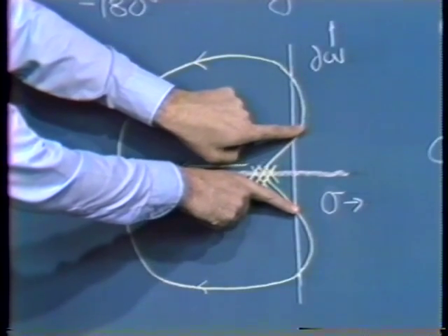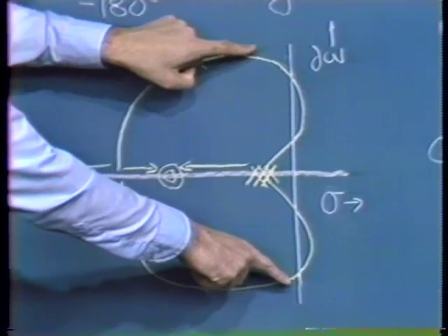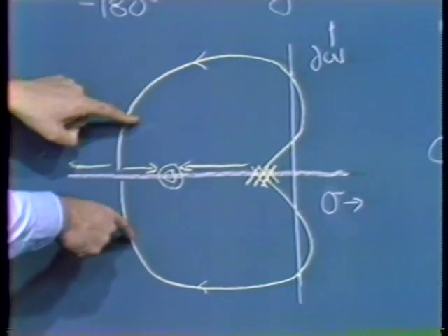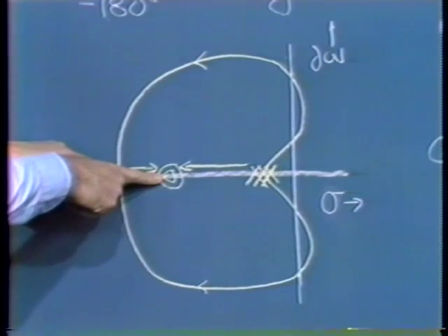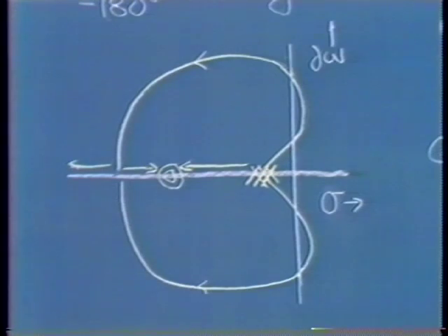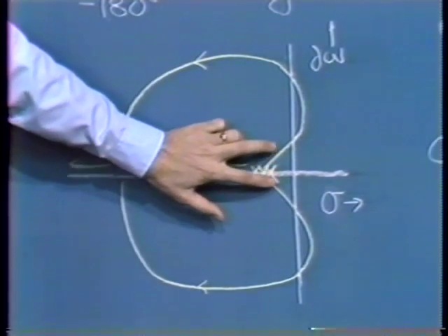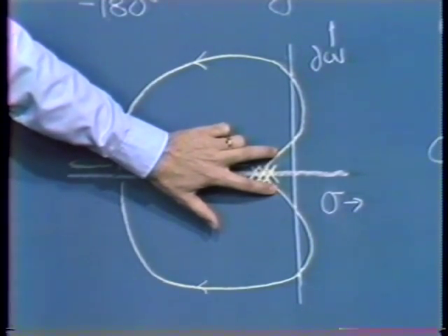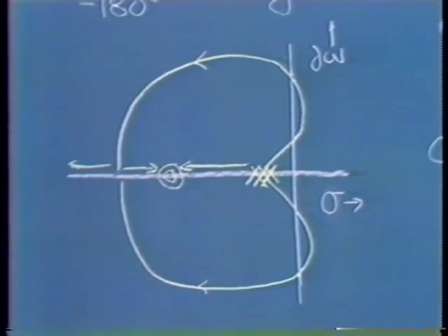We recognize that for larger values of the A0 F0 product, the branches circle around, eventually meet on the real axis. One of the branches heads toward one of the zeros at this location. The other branch heads off along the negative real axis. So if we looked at the stability of this sort of a system, we'd find that it was stable in an absolute sense for small values of the A0 F0 product. All 3 of the closed loop poles would lie in the left half plane.